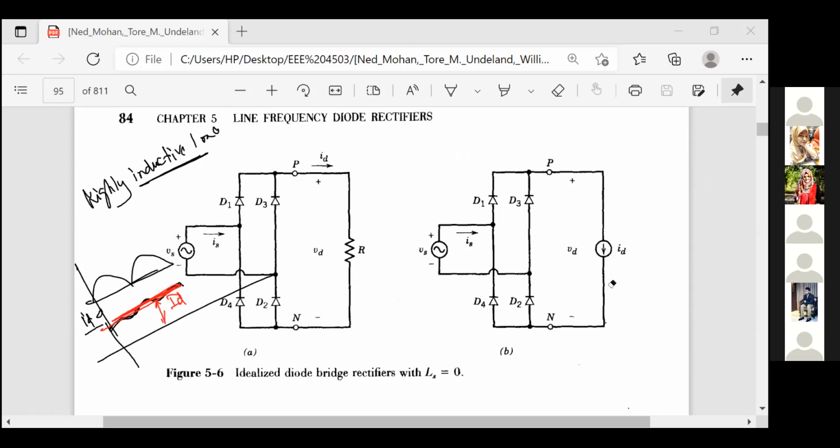A large DC motor has a resistance very small compared to its inductance, and it has a back EMF. If we are talking only about the current, the output current can be taken as a constant current. We shall discuss these things now and try to find out the wave shape of the input current.